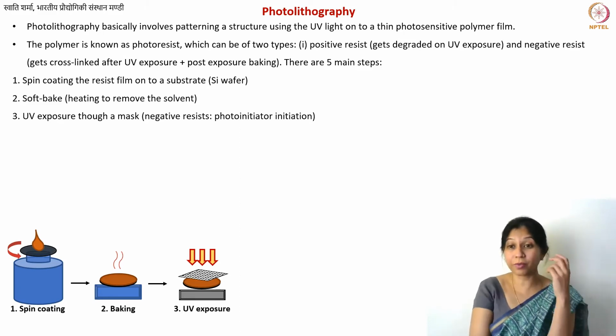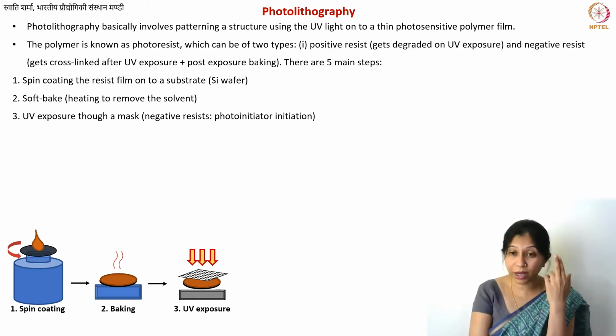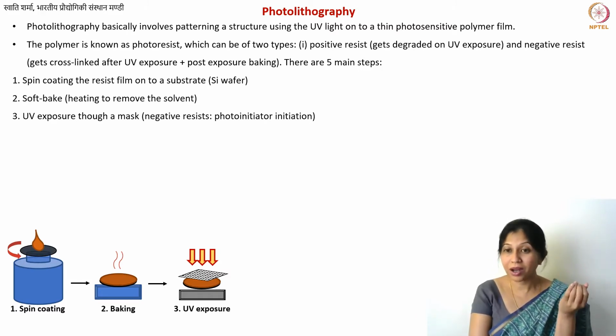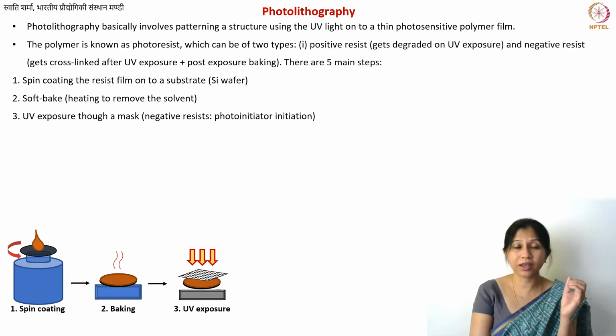But when you want to make structures which are smaller than 5 micrometer in dimensions, in that case you need to use very sophisticated techniques, and you need to do this printing of masks using certain metals. You use things like electron beam lithography just to make the mask, and you use metals like chrome for making the mask as the inks. So now the mask itself can be really expensive, and it's not just about expensive, the fact that you want to utilize it for several batches. You want to have the exact same structures for several batches, so you don't want to damage your mask, and that is why the baking step was also important.